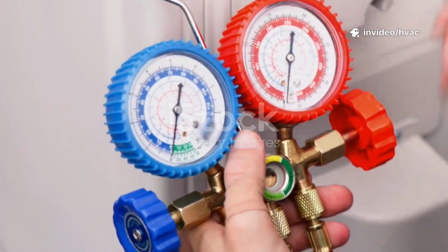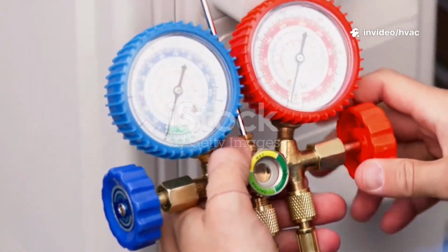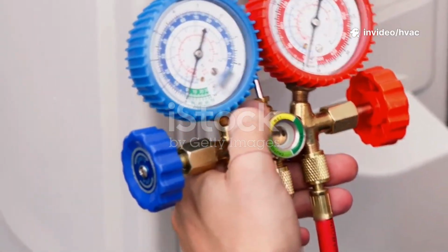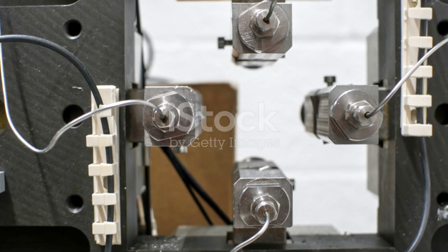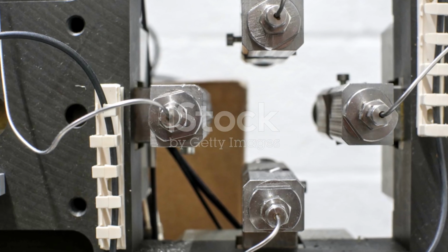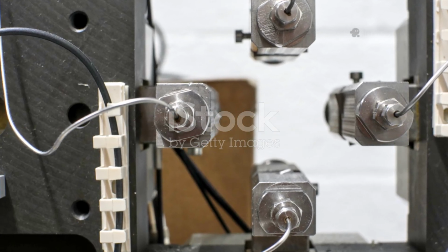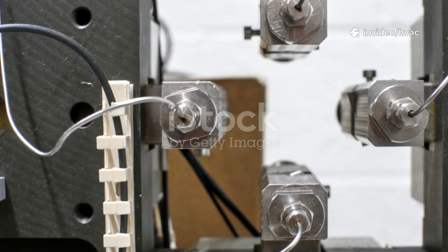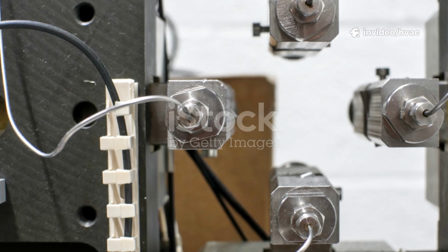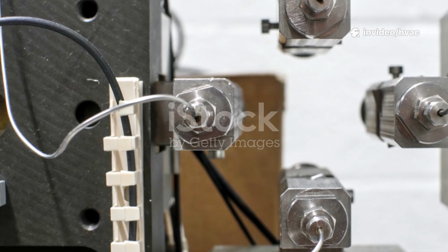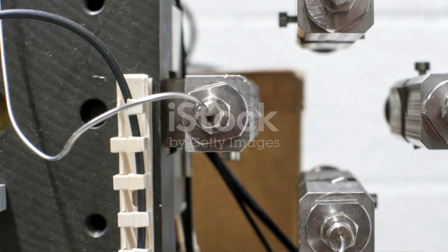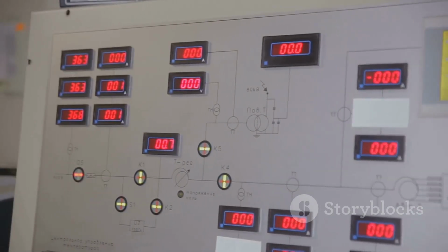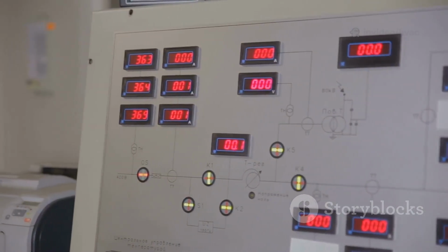Capillary tube sensors are especially popular in large air ducts, air handling units, and mixing boxes, where temperature can vary widely across the cross-section. There's also a more modern approach, electronic averaging sensors. These use several digital sensors spaced out along a wire or cable. Each sensor takes its own reading, and then the system calculates the average of all those points. Electronic averaging sensors are ideal for integration with building management systems, and they're often used in high-tech facilities or where precise control is needed.